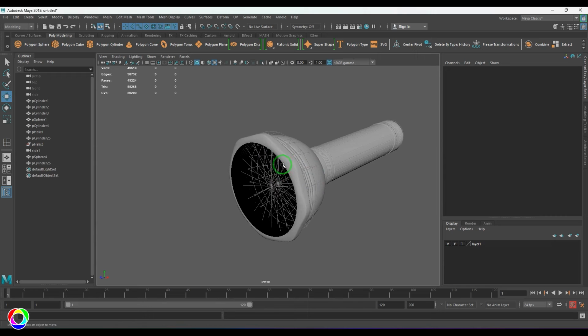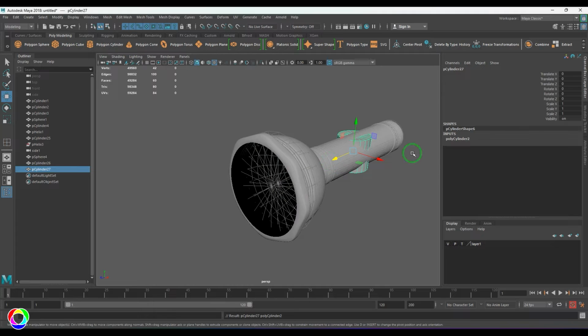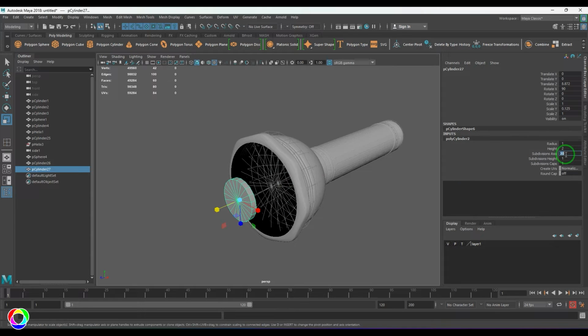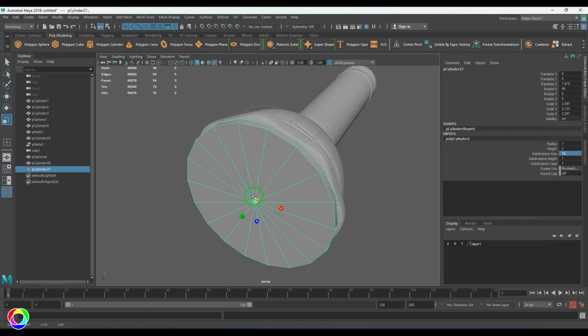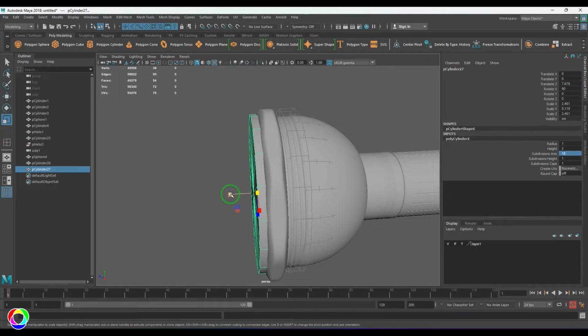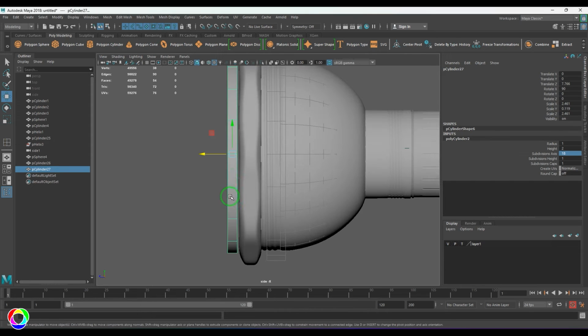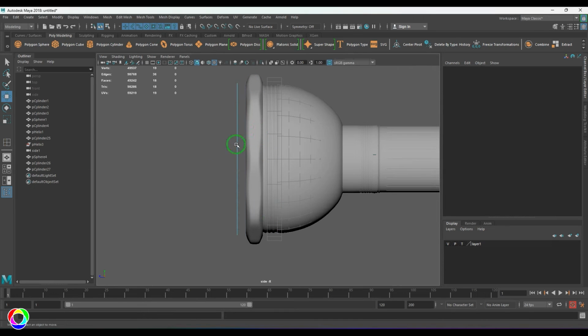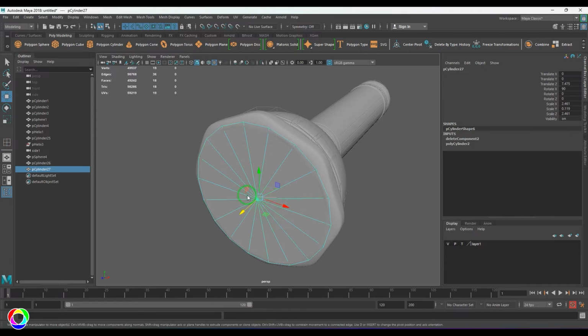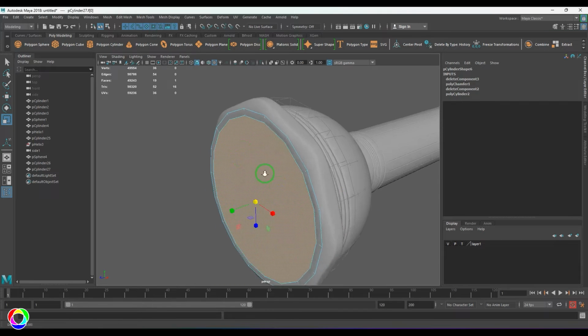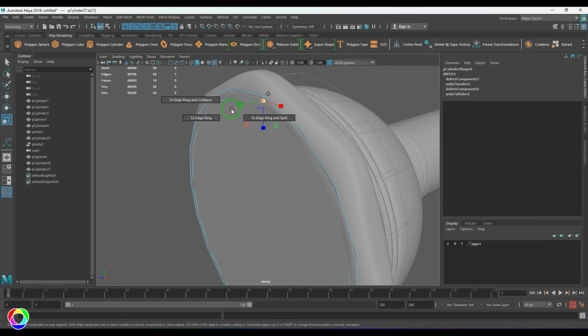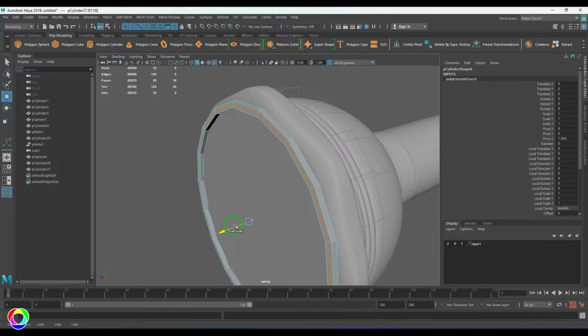Okay, that looks good. Now I'll be taking one cylinder. I can generally take a pipe, but I'll take a cylinder here. I'll be rotating it 90 degrees, and then I'll be taking the 18 subdivisions, and I'll place it there. Okay, and I'll be selecting those faces, and I'll be selecting the vertex and apply chamfer vertex, and then scale that till that face, and then extrude that.